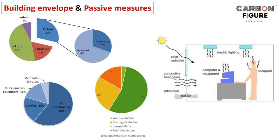In this pie chart, the green, orange, and yellow colors show the envelope heat gain components. Here, the envelope means the walls of the building. What are the heat gain components? You can see wall conduction, glazing conduction, internal gains, and roof conduction. Obviously on four sides we have walls, at the bottom we have the floor, and at the top we have the roof. From the floor nothing would come as a heat element. Only from the sideways and top will we encounter the heat ingress.